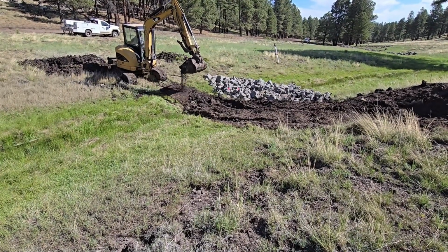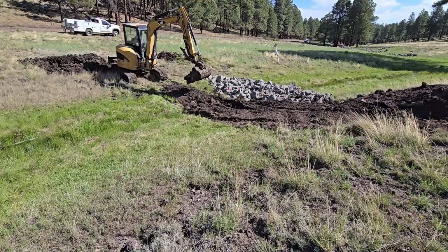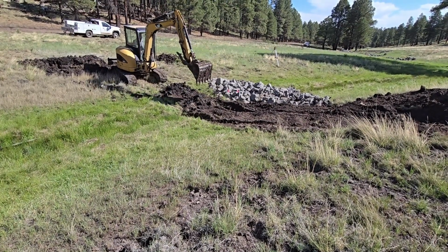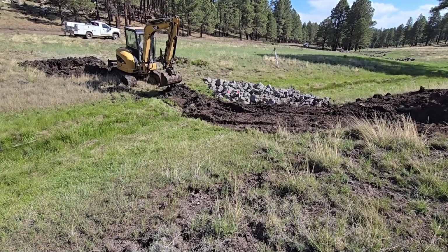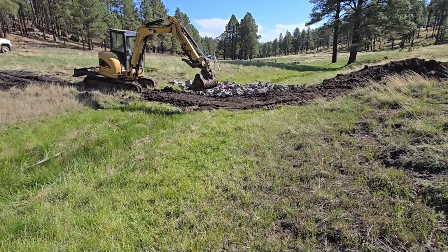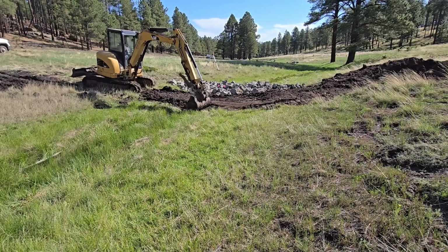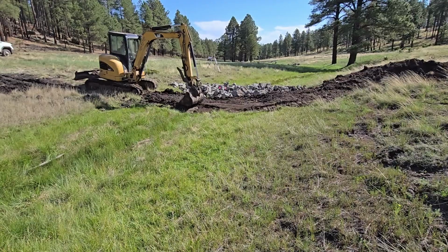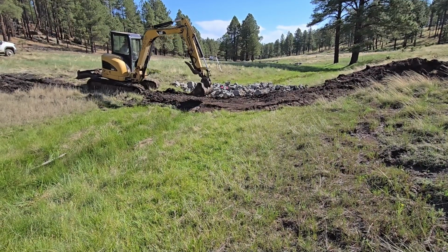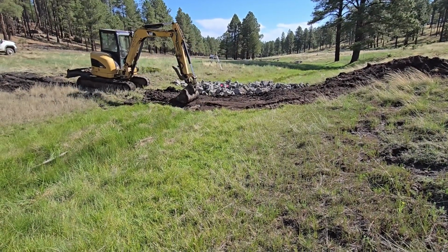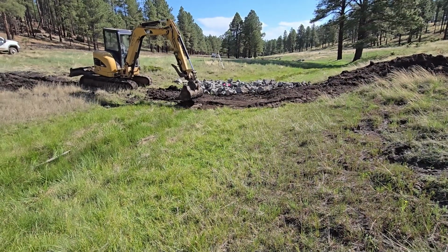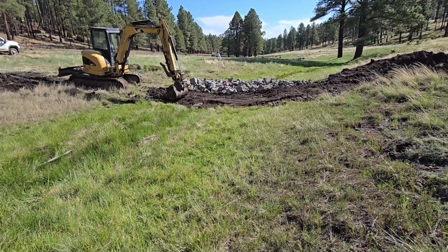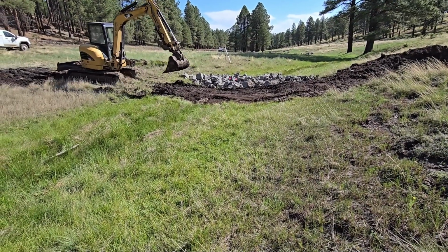The second is that he's compacting the clay returned to the core trench, and this is going to reduce the volume by 50%. Don is also compacting the clay by running over each layer with the excavator. Don now compacts and shapes the top of the groundwater dam so that it's the same elevation as when we started the project. We are careful not to build an above-ground dam that will impound water. He makes a wide floodplain with gradual side slopes and no defined stream channel. We left room to place and embed rock over the groundwater dam and to armor a slope so there won't be any head cuts in the future.